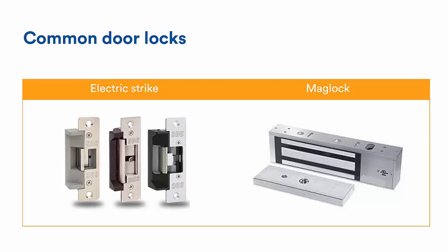Electromagnetic locks are used to secure the door in conjunction with push bars, request exits, devices, or readers for fail-safe applications when code compliance permits. Now, these locks are often the ideal solution for glass doors that need to be electronically controlled and for single standalone doors.